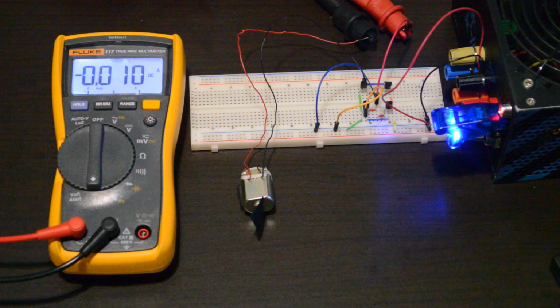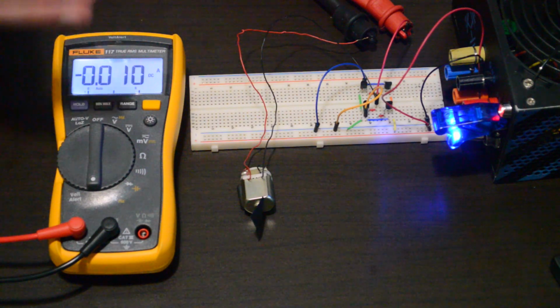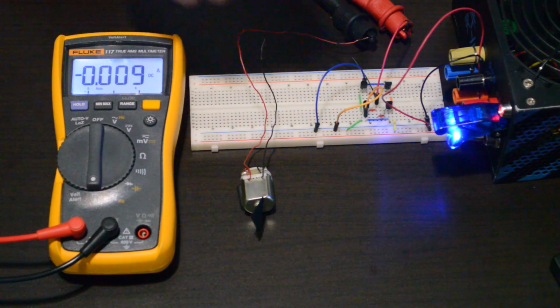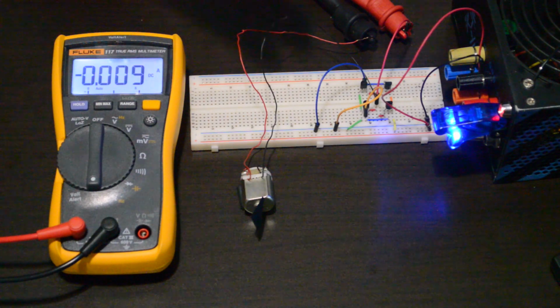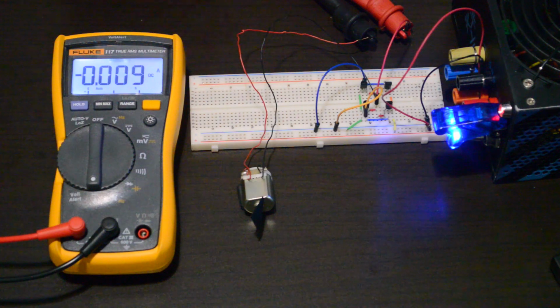So with this HBridge, you can drive a motor in opposite directions, and you can also, by driving both high or low, actually turn the motor off. Now you could do this with, say, a microcontroller. Have an Arduino control those two lines, and that would allow you to switch the different directions of these and control your motor.